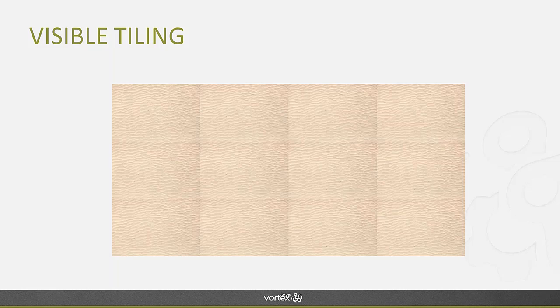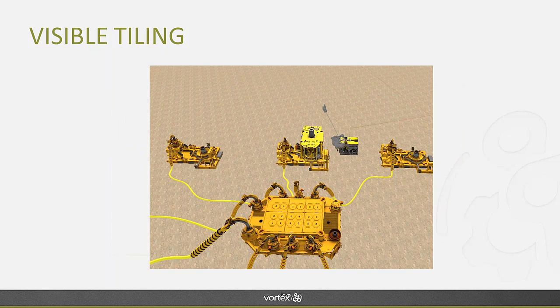You could have seams. Sometimes they're not as visible as the repetition though, such as in the offshore sample scene. If you look at the subsea floor, you can see that there is a lot of repetition of details. You don't see exactly where the texture is joined, but you can see that the texture is tiled a lot of times. But this is a trade-off because from up close, you can still see the tiling, but between that and having an extremely large texture file, which would slow down your simulation, sometimes you didn't really have a choice.